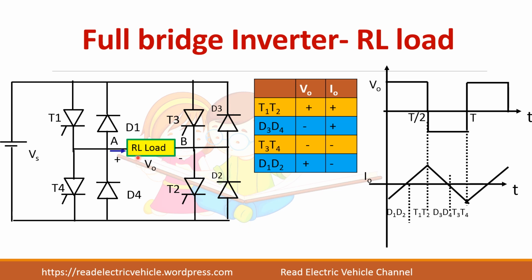So if it is an L load, you will get this triangular waveform. If it is an RL load, depending upon L and R values, you may get a slightly exponential waveform.